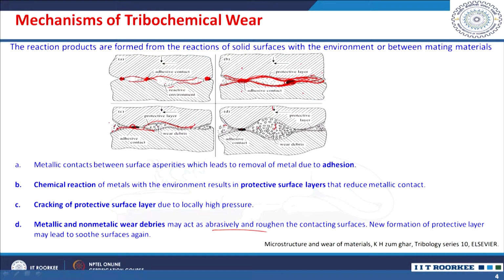But as the pressure is increased at the contacts, the layers are broken and the wear is removed as debris. Then again there is a protective layer. So, it is a continuous formation of a layer and continuous removal of this layer, right. So, they actually contribute to the tribochemical wear.